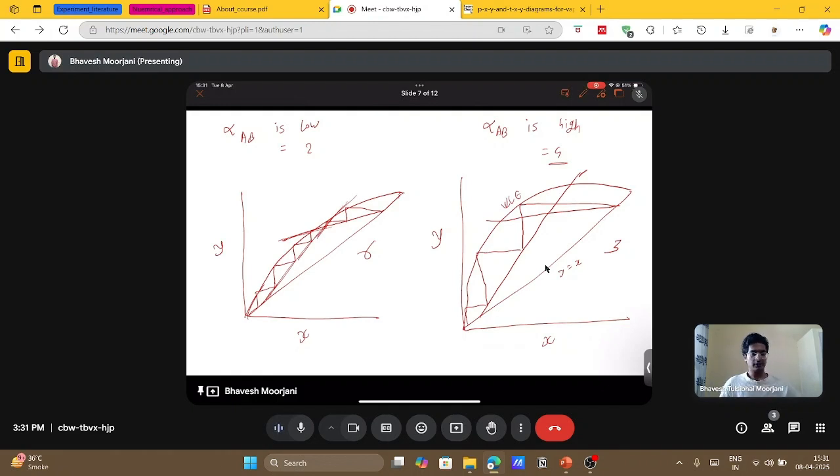Again, there are so many concepts that revolve around these TXY, PXY plots. So it's important to know for a separation what the vapor liquid equilibrium data is, right? So this is its importance. But then how do we compute this VLE data for the different mixtures that we have? So there are 2 approaches.